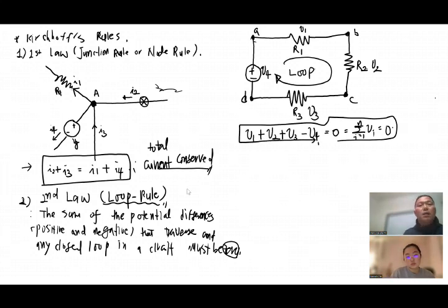So the same as charge conservation or current conservation, the potential variation produced by the circuit elements must be conserved too. That's a powerful tool, because if you add together the potential variations produced by the circuit elements, that should always equal 0. So you have to find out how much potential change each individual component produces, and that can be combined with the junction rule, the first Kirchhoff rule, to find the individual values of resistance or current flow.